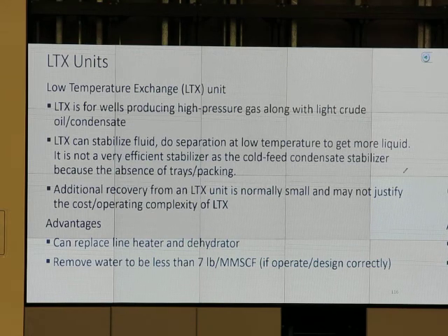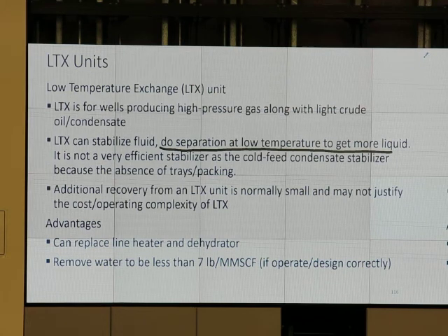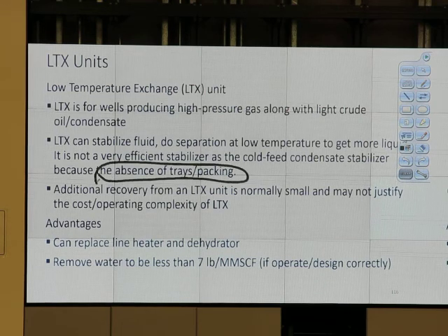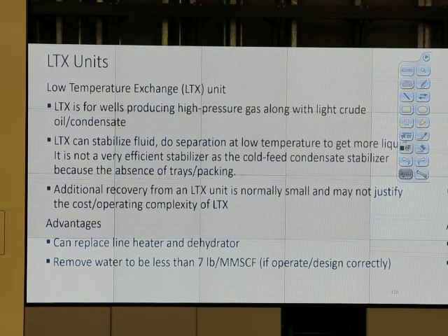Okay. LTX unit is low temperature exchange. It can be used to melt hydrate. It is for wells producing high pressure gas along with light crude oil or condensate. LTX can stabilize fluid. What do I do? Separation at low temperature can get more liquid, so we can get more liquid with LTX. It is not a very efficient stabilizer as a condensate stabilizer because of the absence of tray packing. LTX doesn't have any packing, but it can give us a little more liquid. That's what it is.